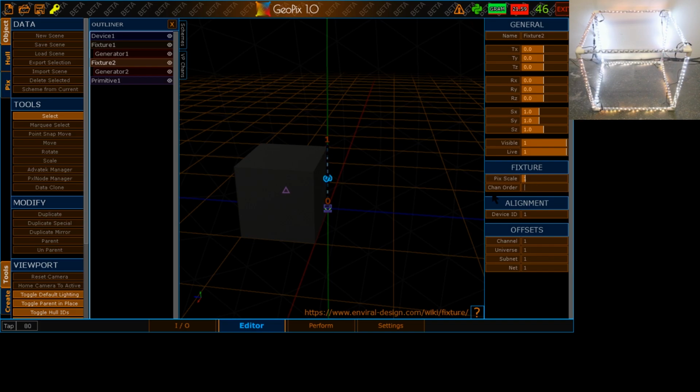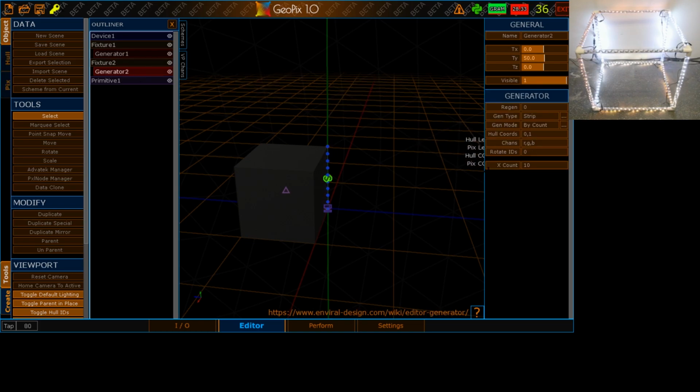Something I'd like to point out is the LED strip color order is actually different. So it's red, blue, and green. So I changed that, and now we're going to change that to 37 LEDs. And you can now see the very back corner is lighting up. That's great. So that tells us we're starting in the right place, and we have the right orientation, so we can keep moving.